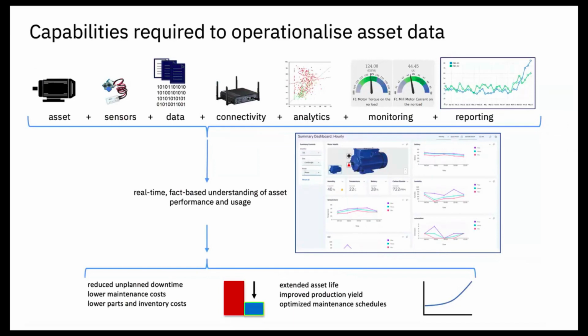And whilst that actually sounds easy, and really it is in many ways, my suggestion is to really start simple. It's this idea of starting to flow data from the sensors within an asset, or the telemetry data that an asset is giving off, and ingest that into a data platform, and then start to apply simple things such as a rule-based threshold to start getting a feel for what that asset is sending through.